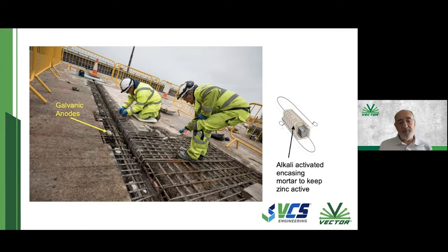Okay, so there's a typical repair, if you like. There's a square. You measure all those bars, the area of all those individual bars, and you divide the surface area that you've exposed by the area of all these steel bars. That gives you the steel density. I imagine that to be quite a high steel density of over 1. And then you measure the perimeter, divide by the spacing that you've achieved from your spacing charts, and that gives you the number of anodes that you need to set out at the perimeter. Same if it's a straight line, if you like. The perimeter is measured along here. So that gives you the number of anodes that you need to install.